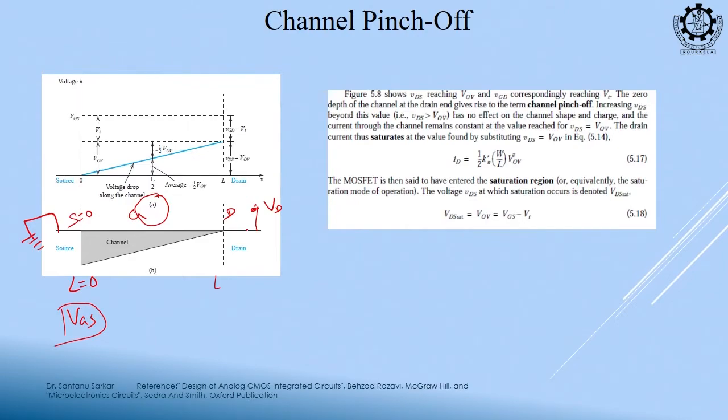The more I come to the drain side, the drain potential is fighting with this vertical gate field. So, suppose at position x, due to this drain potential, after which voltage is your channel forming? VGS minus VTH. So, at least you need this voltage so that your channel is formed, right. Then at the position X, due to this drain potential, let us say Vx is coming.